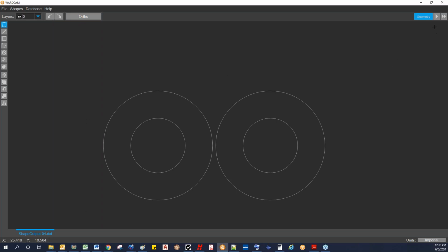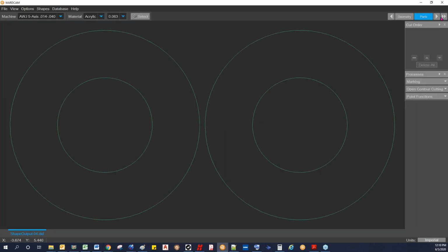And we'll go ahead and at this point, hit our next button. So on the screen here, part screen, you select your nozzle orifice combination, your material, and your thickness. And we'll get more into those here in a bit. Once you've done that, top right-hand corner, you can hit your next button.